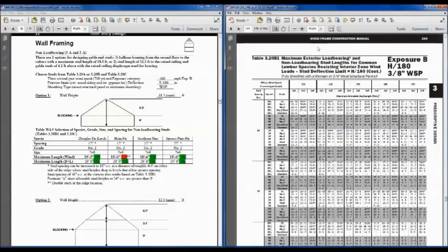those bending design values. The other thing I need to share with you, and this is something we get questions on all the time, is do these stud tables account for combined bending and axial loads? And the answer there is no, because we have an interpretation from the ASCE 7 Wind Loads Committee that you do 2 checks on studs. One check is the check for combined bending and axial, but in that case, for the wind loads, the bending loads for that combined bending and axial are main wind force loads, which are much lower than component and cladding loads. The second check, which we're doing here in this table, is bending only using component and cladding loads.